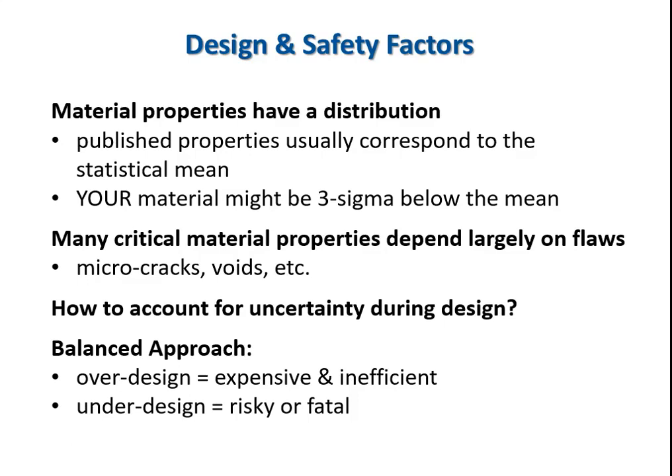So using a safety factor just accounts for all of this stuff that, while it may be possible to find out, it's not always practical to find, and in some cases, might not even be possible. And so a balanced approach to design and safety factors is not to assign so high of a safety factor that your design is impractical, it's too heavy, that can have energy consumption consequences today as well as cost, but certainly isn't unaffordable. But you also don't want to under-design to the point where one of these unknowns can rear its head and cause an in-service failure.